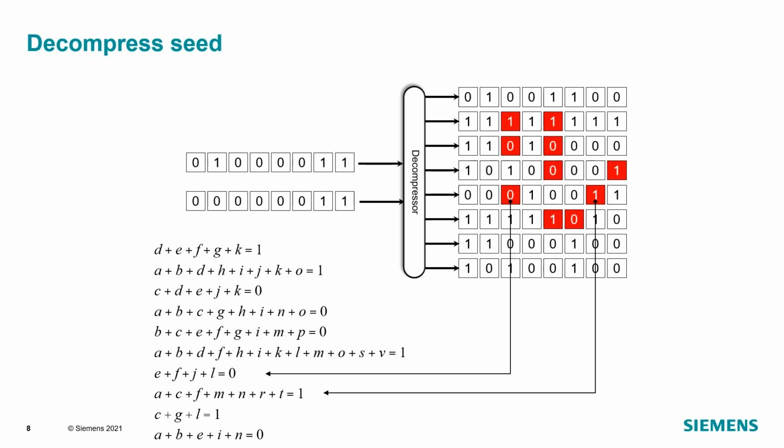Our ability to solve those equations for a given distribution of specified values and the number of inputs depends on the architecture of the decompressor, which defines those equations. There has been a lot of work done by my team to develop algorithms for design of very efficient decompressors. In particular, how to select appropriate polynomial, where to put the injectors, how to configure the phase shifter to achieve the highest encoding capacity with the smallest amount of hardware, etc., etc. This research has been published extensively over the years.